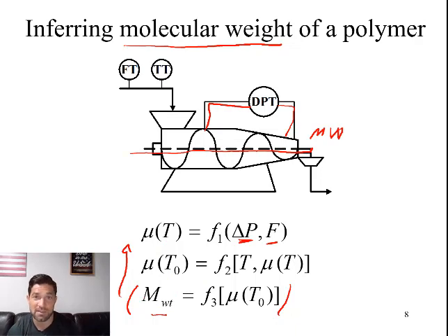Now remember, as you're doing this, at least every couple of hours or every day, you're probably going to make measurements of the polymer and take corrective actions or refine your inferential control correlation, to maintain your molecular weight where you need it to be in order to sell your product at the right value.